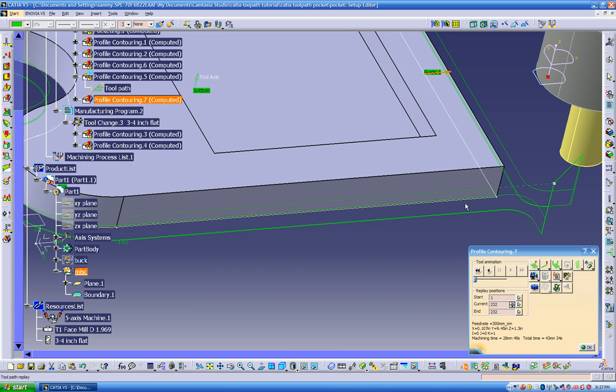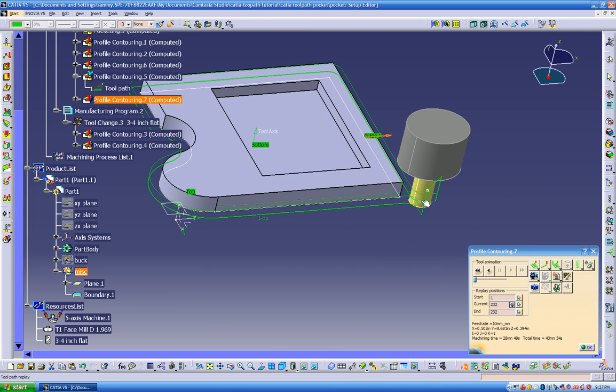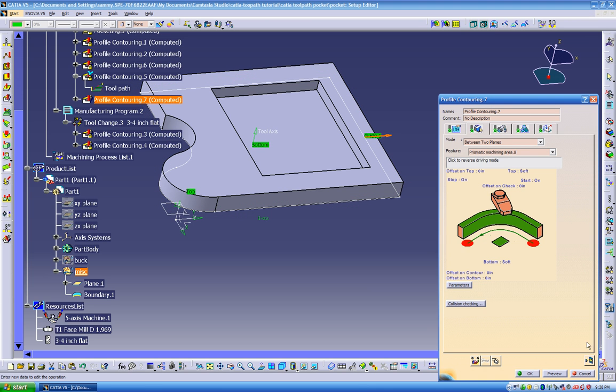But you can input limiting. If you don't want the tool to start on the edge of the part, for example, you want to bring this tool on this point, or you want to start over here, what we can do, we can go to this option over here. So we have two entry points. We got the entry and an exit. You see the arrow right here. Now if I go to the exit point, knowing that this is my entry, watch what's going to happen.